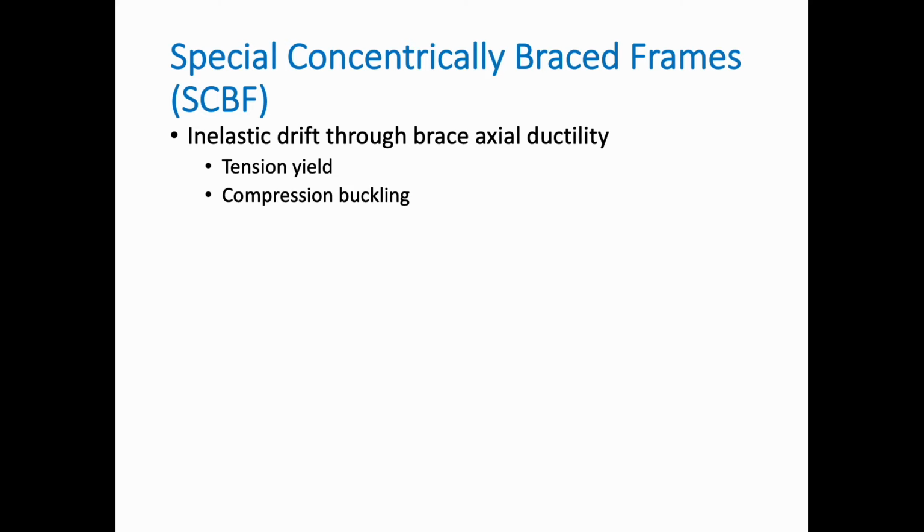Seismic load is a reversible load, so it goes back and forth. So the same member will be subjected to both tension and compression buckling. And these two, although they are opposite in the sense of the direction of the load, they're not just opposite in terms of what is really happening there, because tension is a distributed strain along the member, whereas compression buckling is in fact a flexural buckling that is happening in the member.